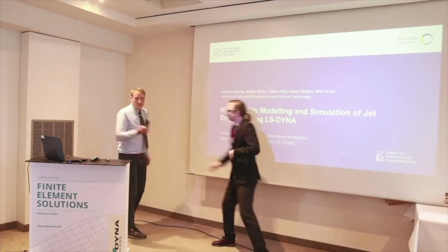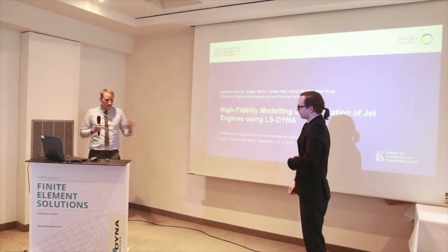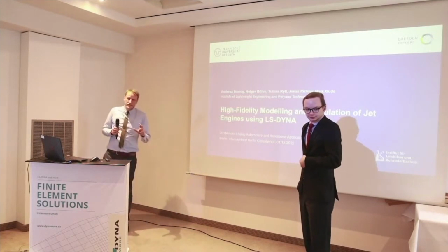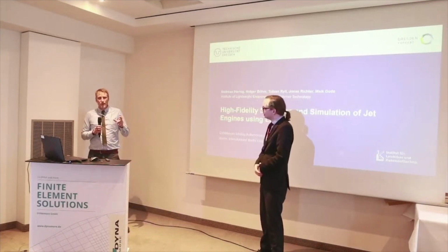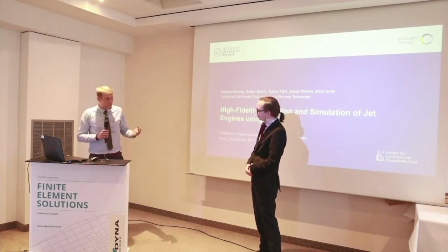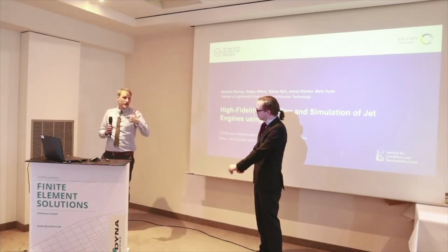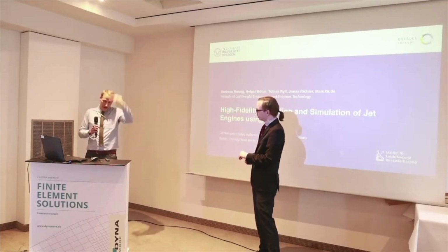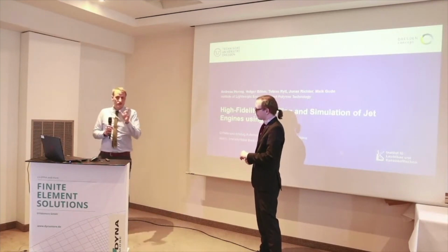Yes, so obviously you have a whole load. LS-DYNA provides a variety of material modeling approaches. In this case, we used a slightly different approach. In radial direction, we used material 54, but not in the way you would think. We used the 1 and 2 directions in tangential and length direction, because we are focusing on the through-thickness shear and failure behavior.